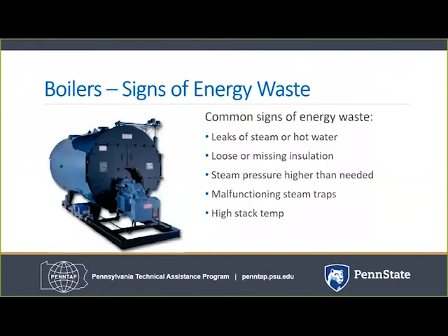Each boiler and steam or water distribution system is unique, but some common general signs of energy waste are leaks of steam or hot water, loose or missing insulation, steam pressure that is higher than needed, malfunctioning steam traps, and high stack temperatures for boilers. The general signs above give an indication of the energy savings opportunities available.